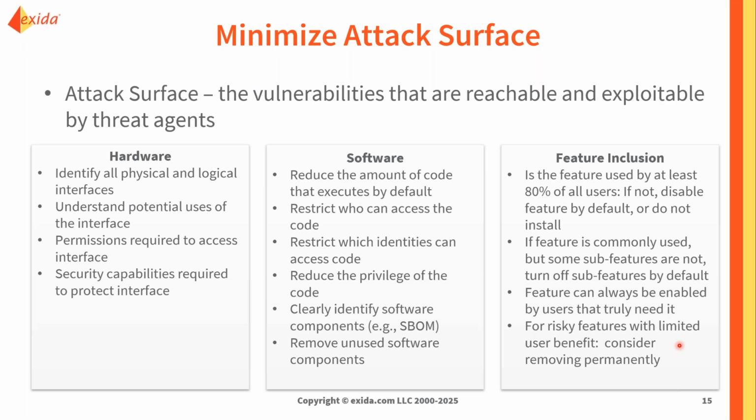Think about how many of the control systems and controllers out there today have pathways for easy remote access. There may have been a time where that was really desired for ease of troubleshooting and making adjustments. But as we understand the security implications today, do we still really want that access to be present? And if it's still included, do we want it to be enabled by default, or should it be disabled?